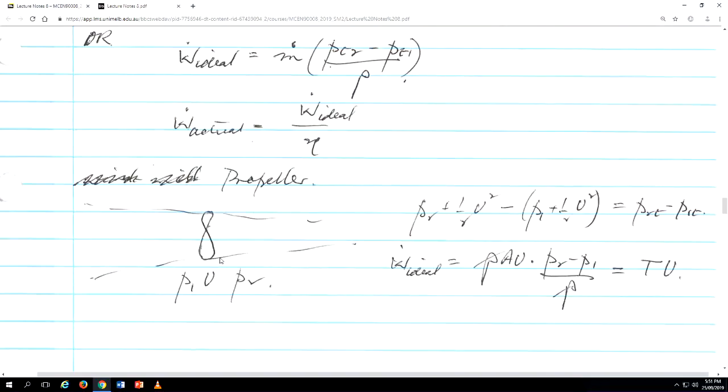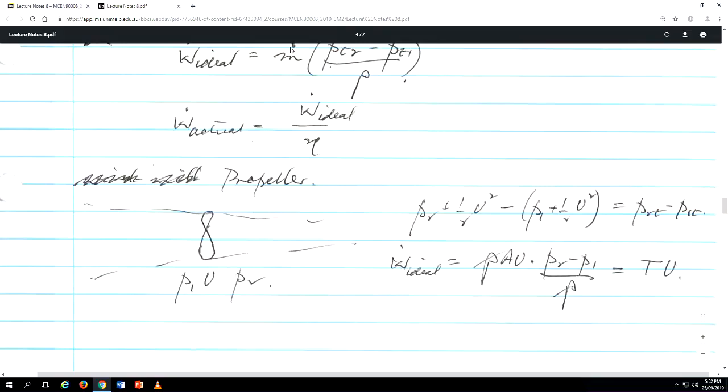The force that's acting is the force that's holding the propeller where it is. If you let the propeller go, it'd go upstream very quickly. So I have to hold it with effectively the thrust, so that the thrust on the propeller is holding it in the control volume, and there's a downstream pressure and an upstream pressure, and they have to balance. The net force on the control volume, because there's no flux of momentum out of it, is 0.